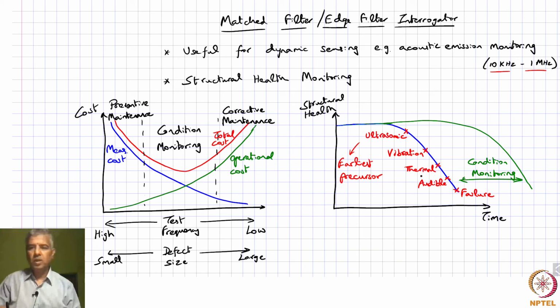Are you able to pick up some audible sounds? Yeah, possibly. Sound waves are nothing but pressure waves, so if you have a fiber Bragg grating exposed to those pressure waves, the fiber Bragg grating is going to get stretched. So if it's put on a substrate, then as the pressure waves are hitting that substrate, it's going to stretch the fiber Bragg grating, and then you can pick up those audible sounds.